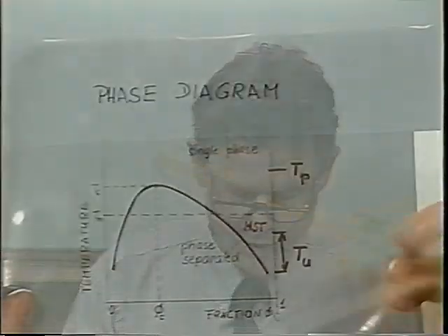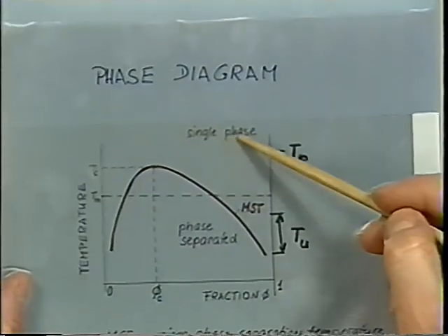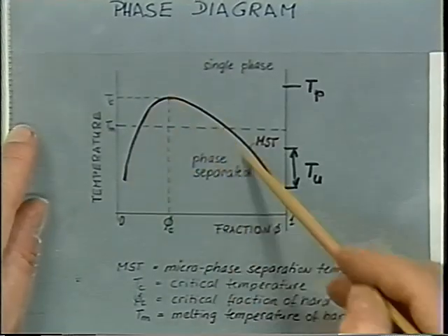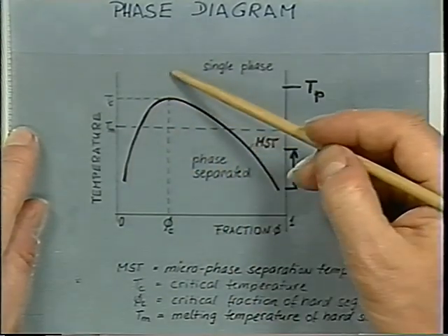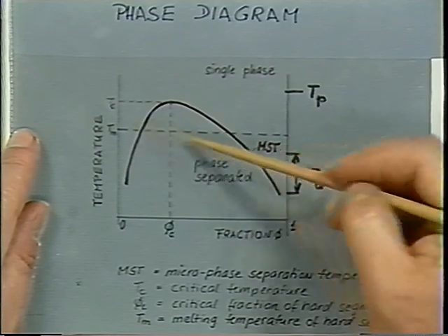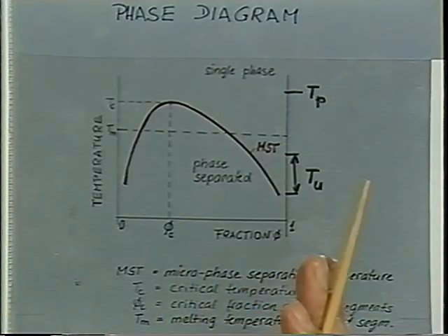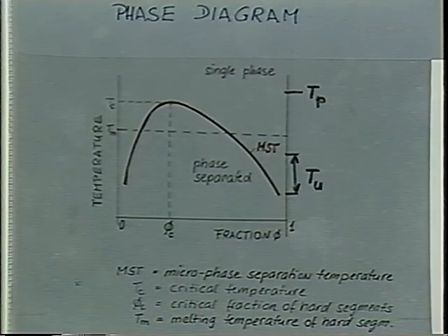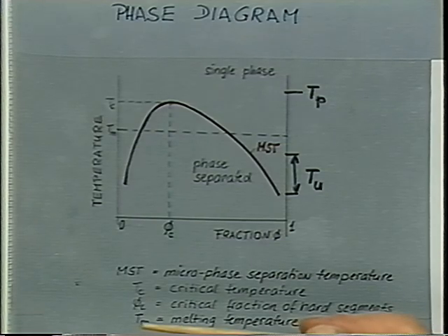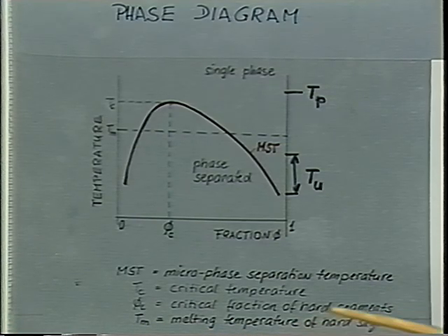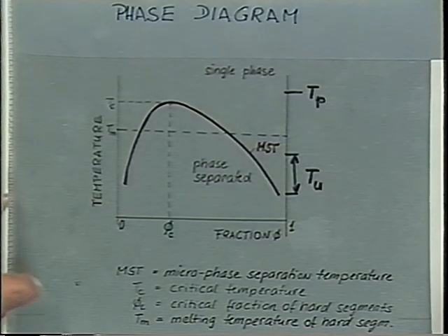We can start in the single phase, if that's a typical coexistence temperature of the block copolymer. We start at high temperature, quench to lower temperature, introduce phase separation, and at the same time deform the material. And this way, as the structure develops, the grains are aligned immediately, and we're getting a very nice uniform single crystal structure when doing that.